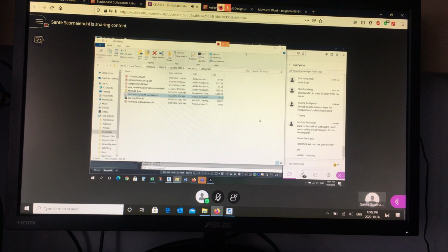So for instance, this semester we're working using the Town of Richmond Hill standards. Next semester we're going to work in the Town of Milton. So we'll have a new set of standards, but we have to look up the same type of stuff, right? What road section am I using? What curb and gutter detail are they using? What's pavement width, and what does that mean? Is it asphalt? Is it edge of pavement? Where do the sewers go based on the cross section, right? So you're looking for the same information to do your work, but the information may be different in the details when you look at a different municipality's standard, right?